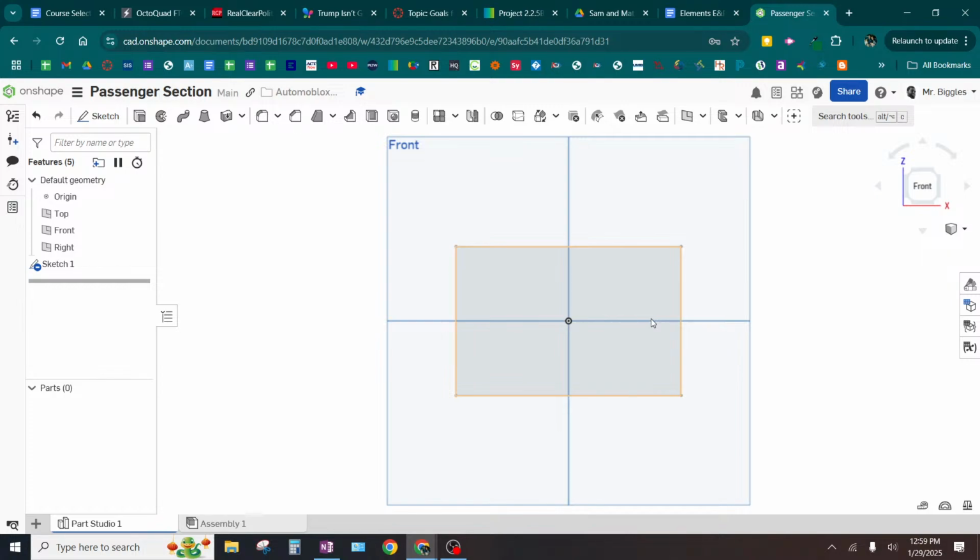Now, how tall and wide is this rectangle? Well, first thing I want to do is take my calipers and close them. Don't hold them closed, just close them, let go, and then push zero. Do we understand? Good. They should be in millimeter mode, by the way, if you're not already. You can just keep hitting that mode button on the left toggle.